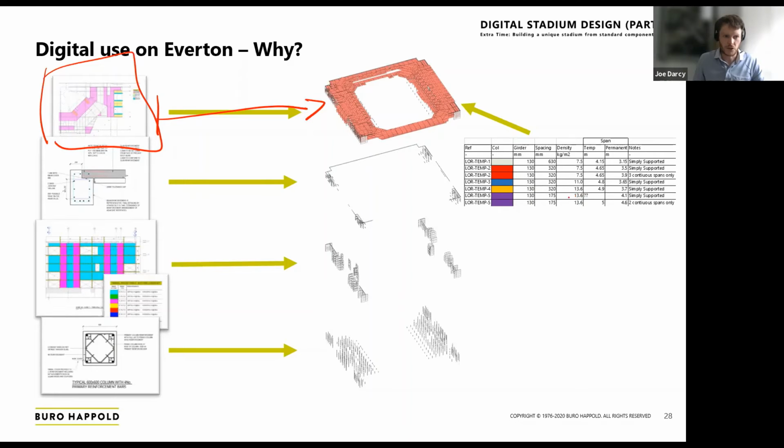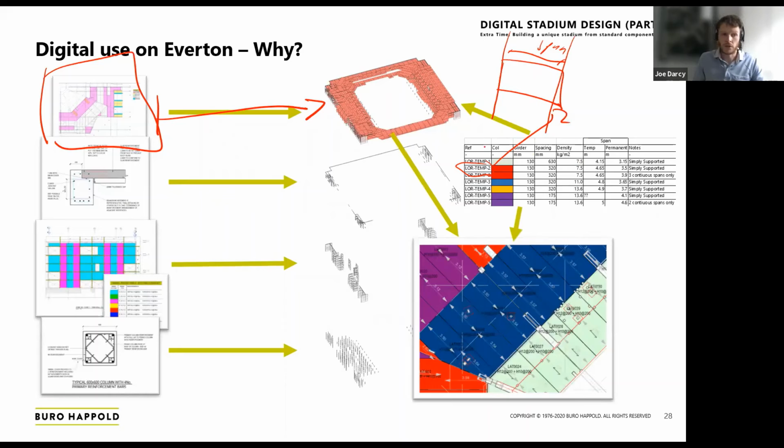We were able to distill this essentially into a load table, and because we have the objects, we know where the plank is and where its supporting beams are, so we can understand the spans each plank has to deal with and cross-check that against the temporary works load table to understand, oh, this needs a temporary works design of number 2, and embed that in the object. Whilst doing that, we also outputted that process.